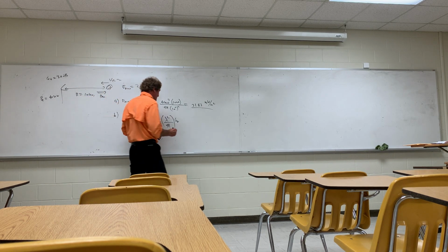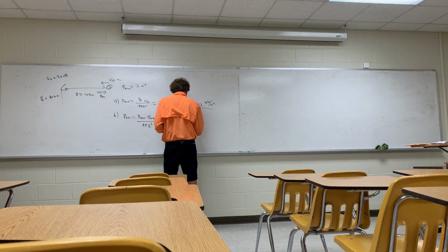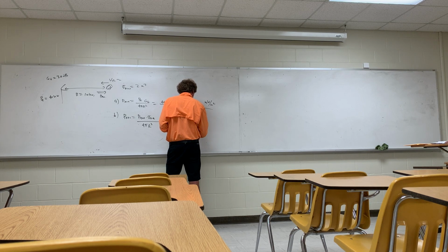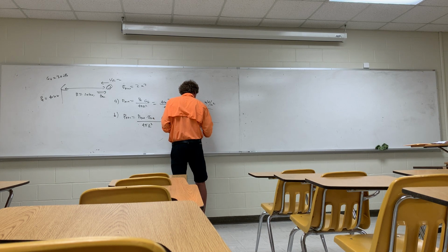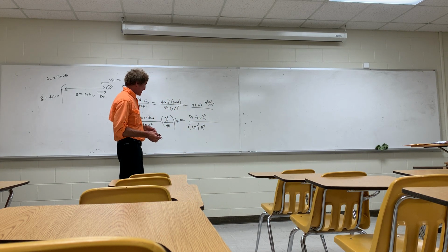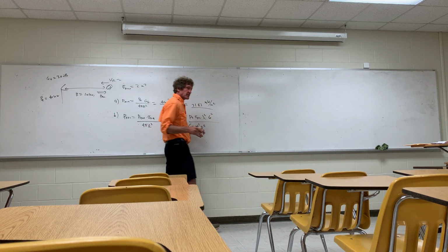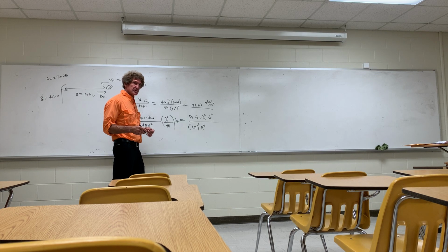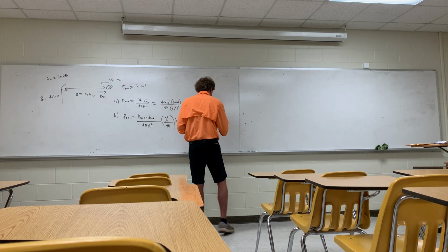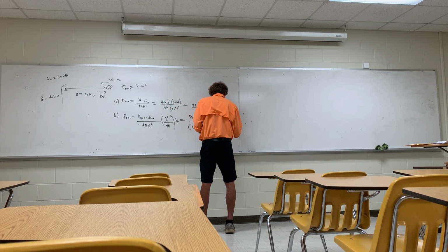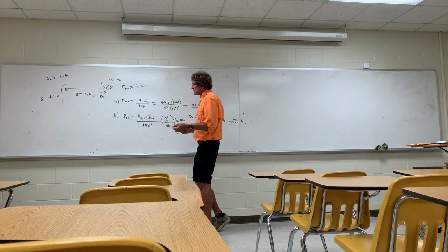If you want to do it your way, you simply take transmitted power times sigma RCS times lambda squared, divide that by 4 pi cubed r to the fourth, times gain squared, because the gain of the transmitter and gain of the receiver is the same, and you get the same thing. Y'all agree with this class? All right. And can you give that? 2.27 times 10 to the negative 11. That would be watts. That's right.